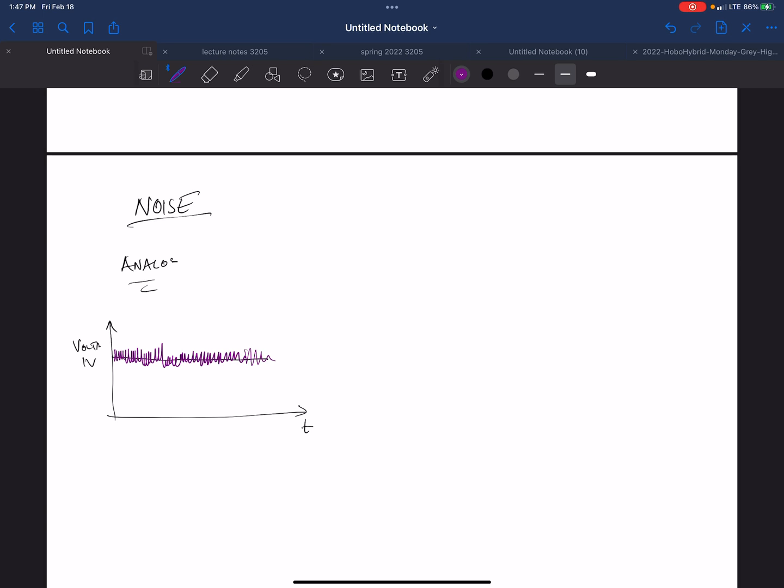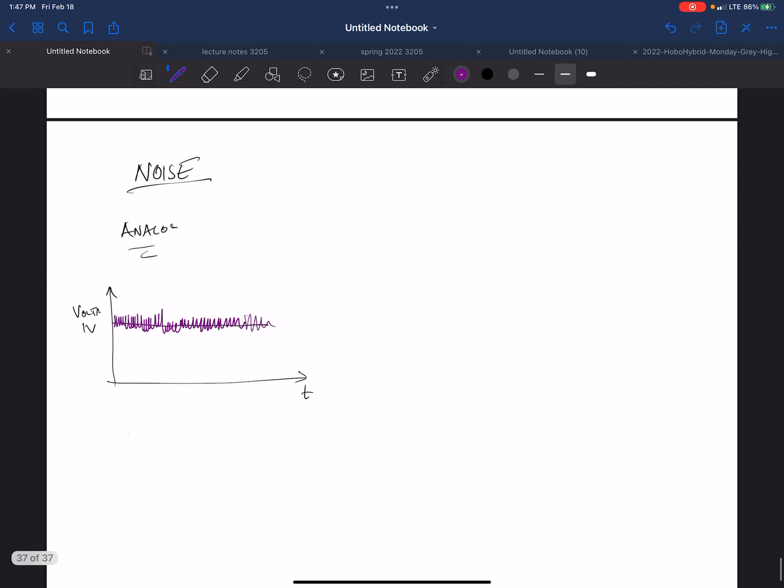This type of noise includes things like thermal noise. This is fundamental. It comes from the Brownian motion of electrons in a resistor. Electrons in a resistor tend to go back and forth, back and forth, even if I don't have any voltage across it. So if I zoom in enough on the voltages, there's this variation in the voltage because these things are jumping back and forth.